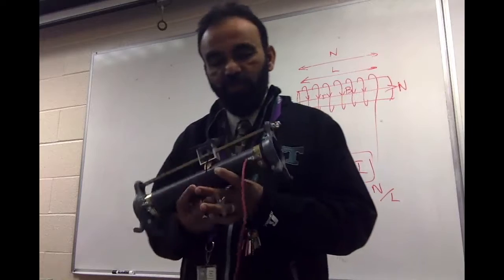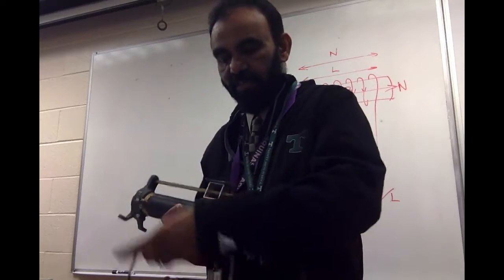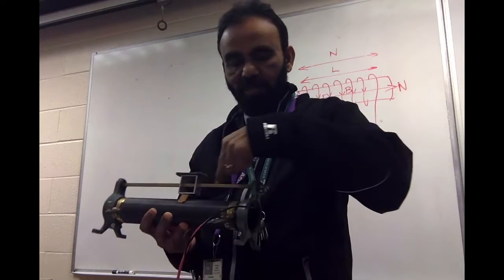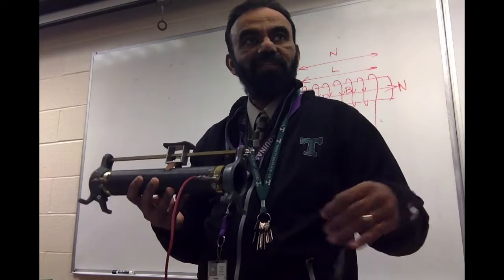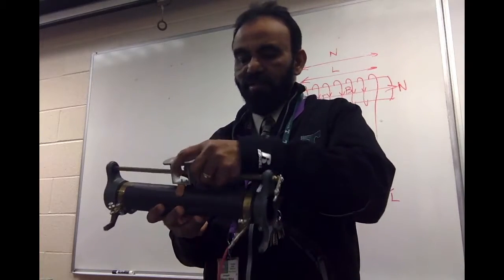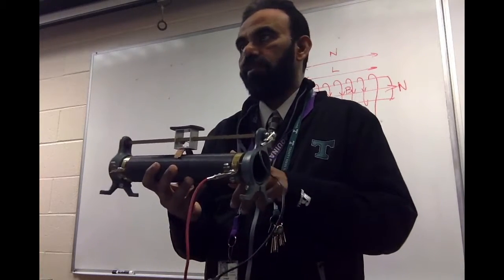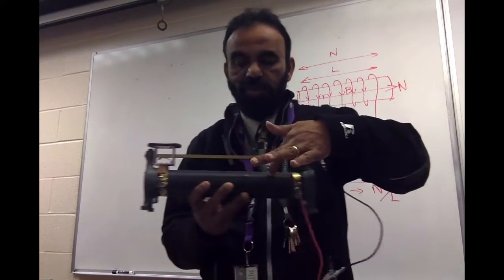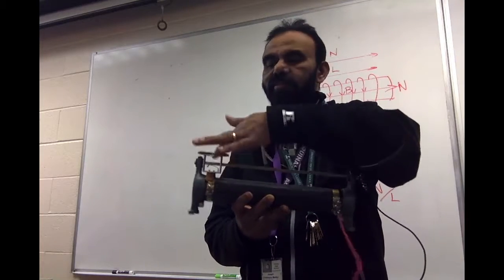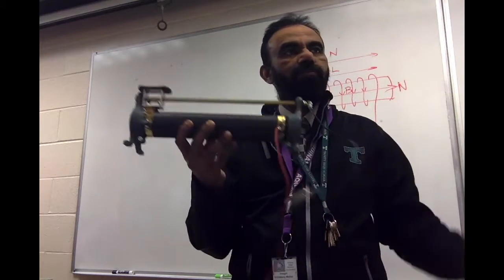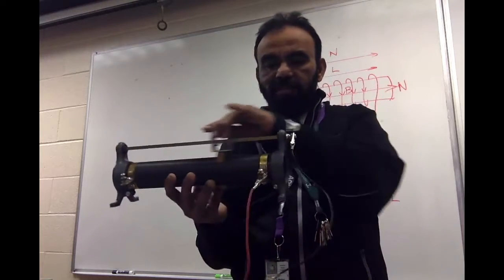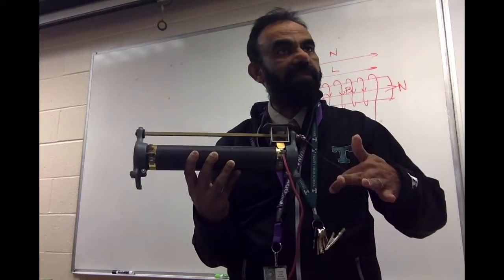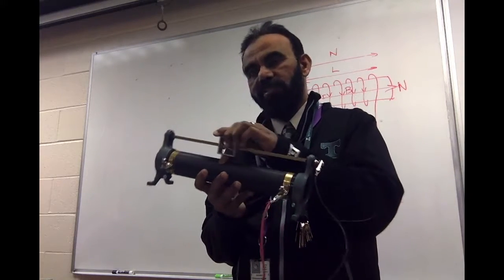Okay, if I connect between those two, look what's happening. The current goes in and through the coil. When it comes here, it gets picked up, and then it comes out from there. You get it? So right now, if I keep it right in the middle, the resistance is probably around 45 ohms. If I take it all the way to this end, see which way the current is flowing. The current goes all the way and then gets picked up. So it's fully 89 ohms. If I bring it here, it is 0, because the current comes here and gets picked up. So this is more of a variable resistor.